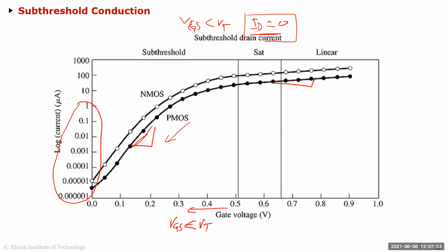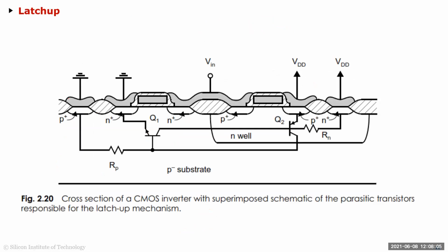If they're doing a poor job, obviously it'll be off. But the model itself is capable of modeling subthreshold, which was not the case in pre-BSIM3, BSIM2 region. Okay. All right. So I'm kind of randomly covering different topics now, which are very useful while designing. Also, kind of pet questions for people for interview questions as well.